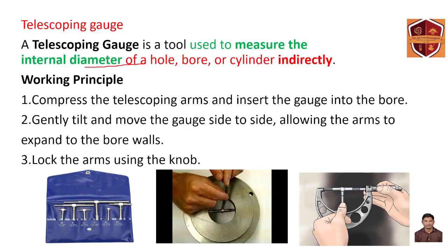You can oscillate from top to bottom. If any errors occur, it can easily indicate that place. If any gaps are available here, that is the error spot. After taking that reading, you can finally check with the micrometer. By using this micrometer, you can easily find out the reading.